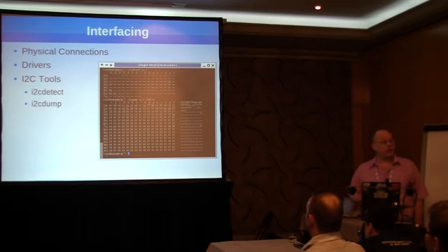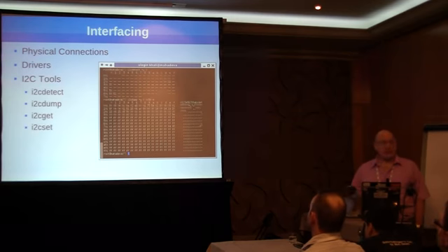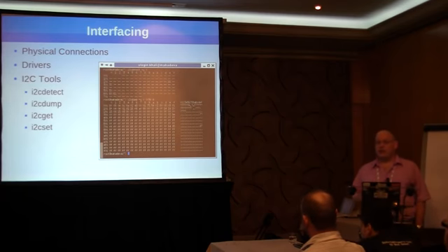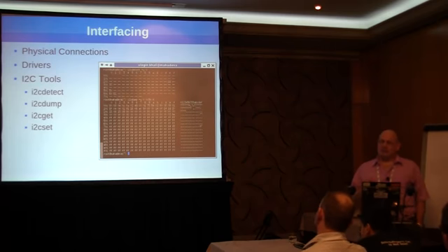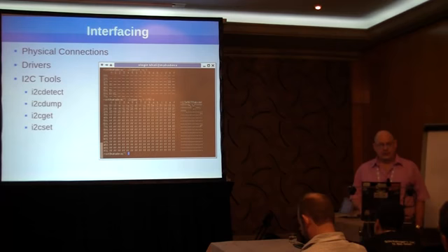In addition, there's also an i2cdump command that actually works with I2C EEPROMs. You can actually dump the data from an EEPROM and see the values or cat it to a file or work with it, whatever you want to do. In addition, you can set data and get data for specific values. Now this makes it very easy to work with serial EEPROMs and other I2C devices from user space. Do you really want to do that all the time? No, but with this being specifically stated for board bring up and doing diagnostics and prototyping, it's very easy to use and work with.